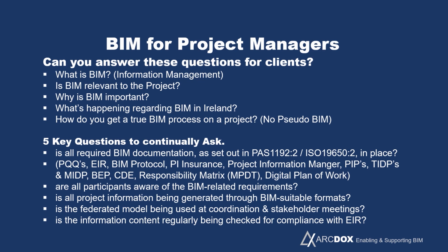The task information and master information delivery plan, as I said, is a tool to manage all the information files that are going into the common data environment and to track progress against those. The BIM execution plan is a formal response from the supply chain, from the designers and the contractors, that can be assessed. So again, these are really important project management tools.